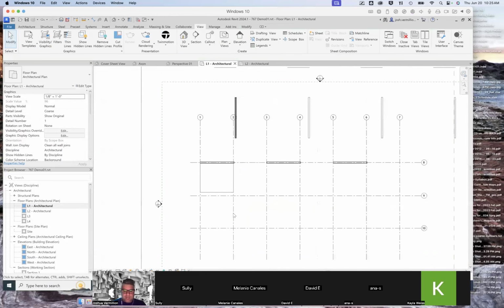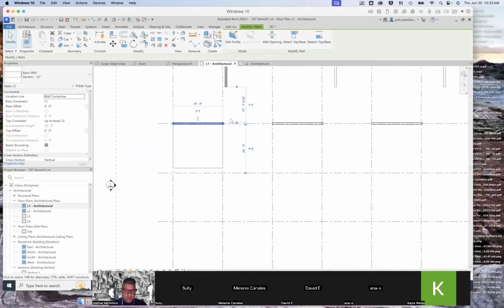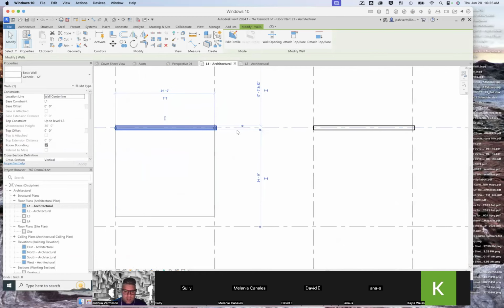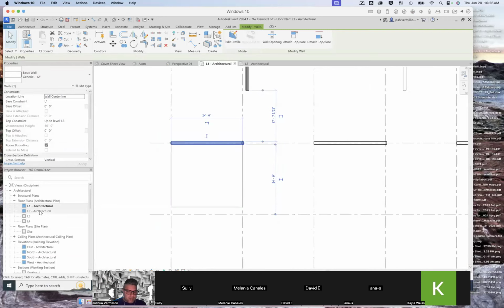All right, so now I've updated these things. And depending on how you draw these things, like if I draw this wall, I could always try to make the relationship with this wall always fall along this center line. The wall center line always falls along this grid line, right? Or I could have some sort of other relationship with it. And then if I move the center lines, the grid lines around, then the walls and things like that will update with it, right?